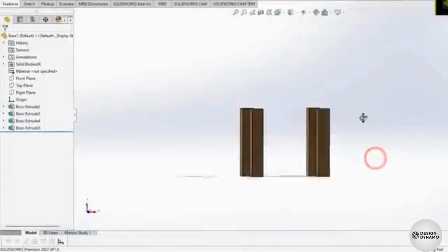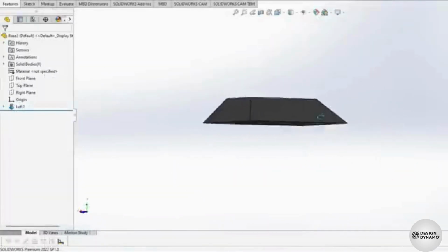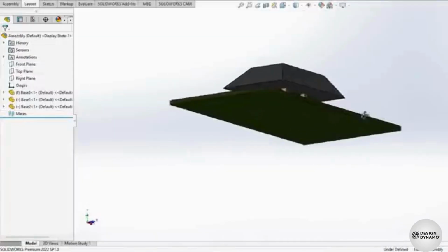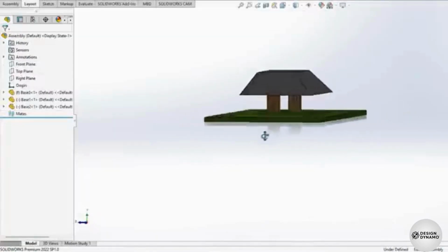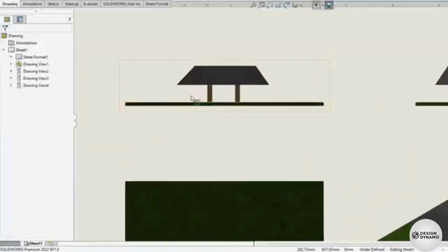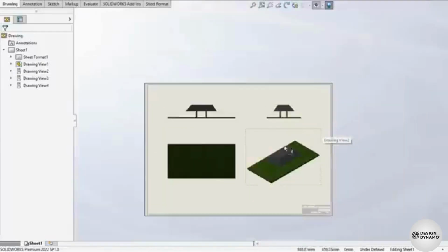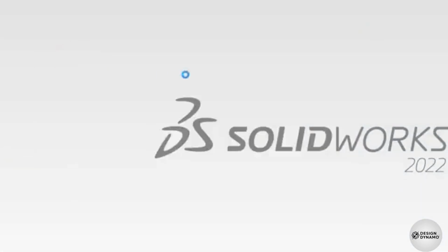Projects. Part is used to build 2D drawings or single 3D components. Assembly to combine these 3D components together. And drawing to get a 2D description of any built component, very useful to realize documents. To see how to use SolidWorks, let's start with a part project.